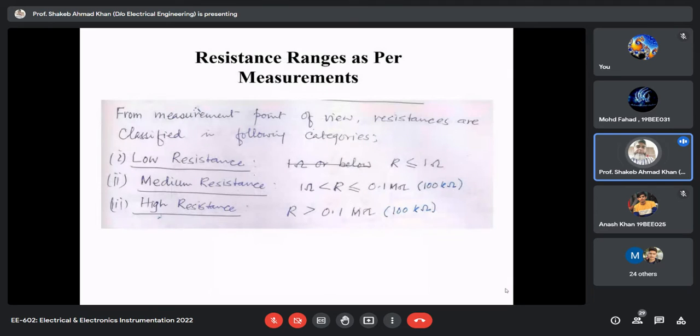See, our range is this. This is the range of medium resistance, 1 to 100 kilo ohm. So what I'm saying is that the first circuit is good for the higher side. This is the range actually. For the higher side, obviously, because your unknown resistance is in the denominator of the error expression, when your unknown resistance is high, your relative error will be less.